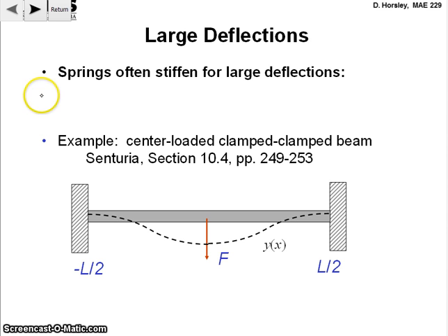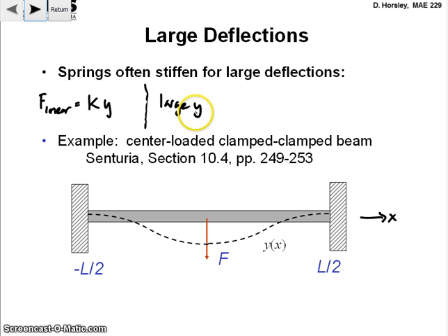So a linear spring we could write as k times, I'm sort of reluctant to call it, let's just call it k times y for now, okay? Because when we defined it before, x is basically the distance along this direction here, and we have y of x as this deformation function. So at large displacements, then f spring is linear, right, because it's basically constant times y, so this is the equation for a straight line.